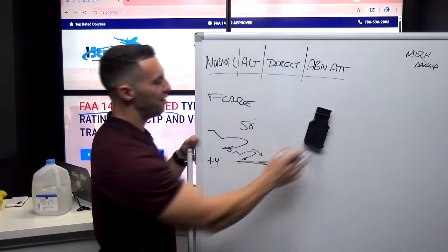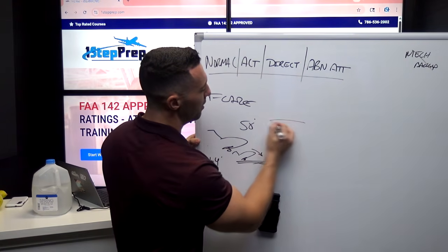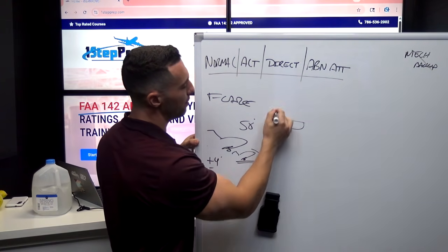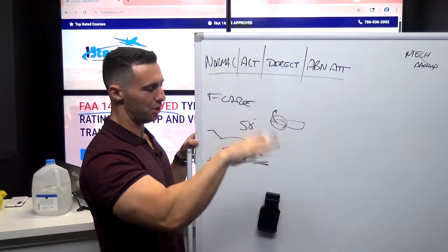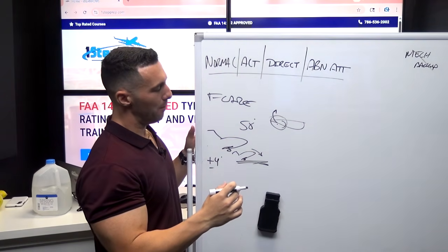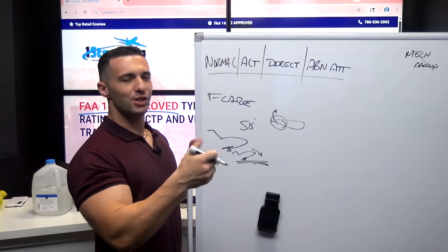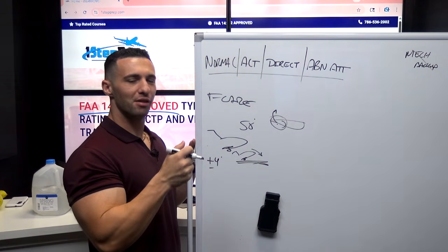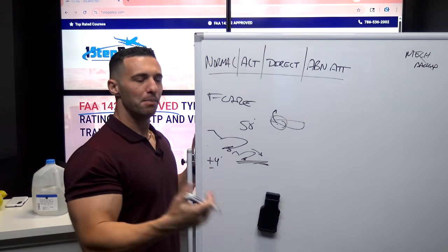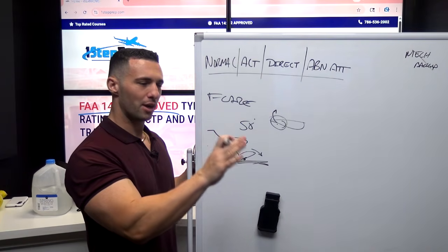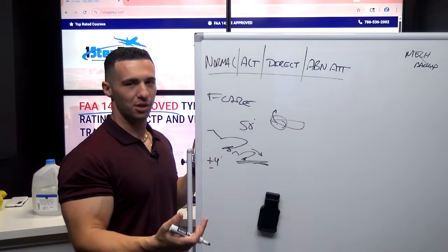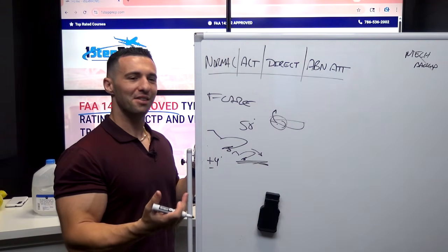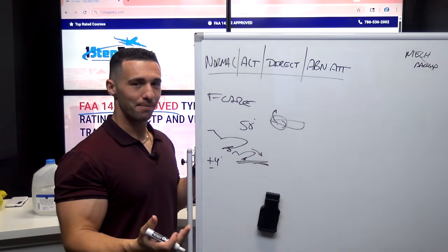And if you were to put a high-speed camera on the elevator back there, what you would see, of course, is the elevator deflecting nose up and then back to the neutral position, nose up, back to the neutral position, up and down like this. The reason you're having to continually apply this aft input is because you're trying to soften the landing, because there's a natural tendency for the nose to want to come down as the elevator returns back to the neutral position. Well, we just learned that the side stick is actually commanding G load.